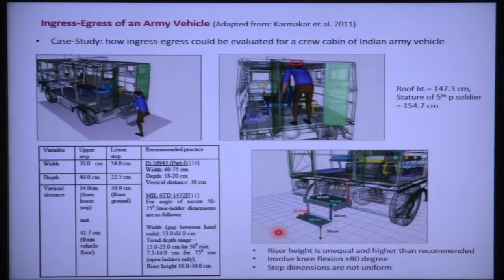As this riser height is not uniform, while the army personnel are going in a hurry or carrying load and going inside or coming out, due to that rapid movement they may fall down. There is a chance of accident due to this uneven distribution of the riser height.